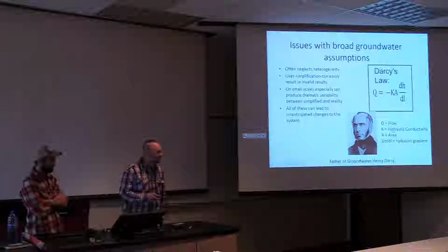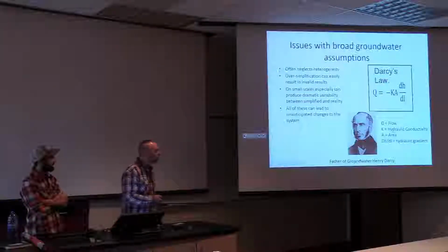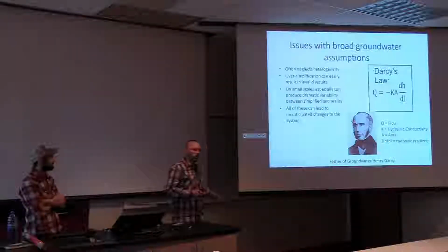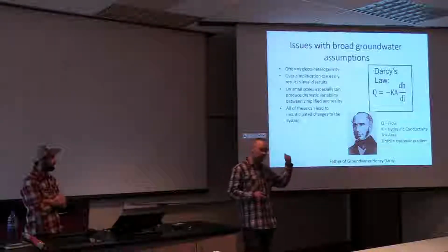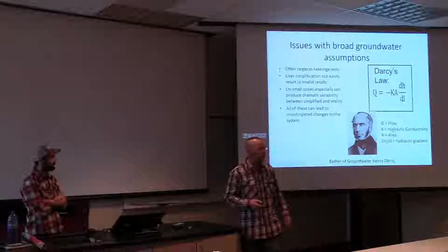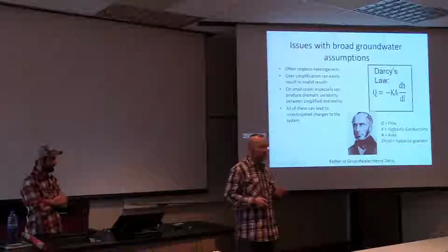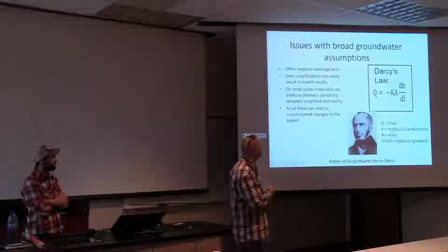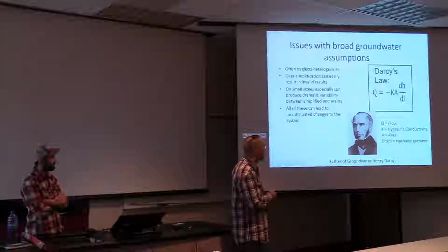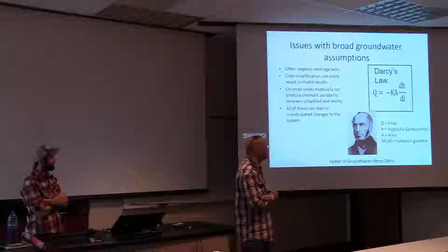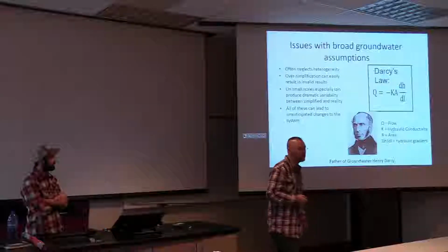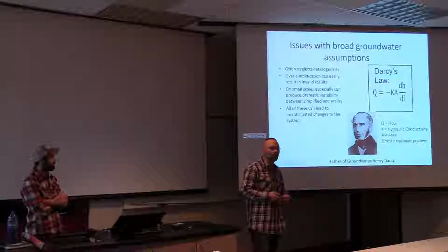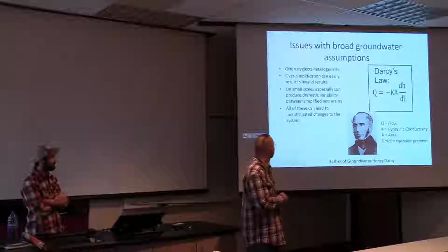I'm going to give you a little baby lesson on groundwater flow. First of all, the reason we want to go into a more complex numerical model is that we first have to do the more basic Darcy's Law calculations. Now that we're going to do Darcy's Law, I want to talk about how sometimes it neglects and simplifies. This is very simple math, and it takes away some of the heterogeneity that might be involved in the system, and that can result in invalid results.